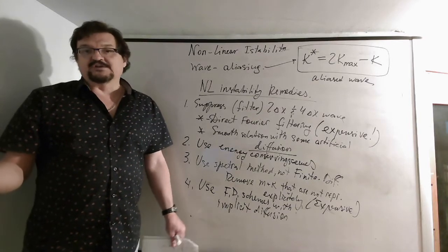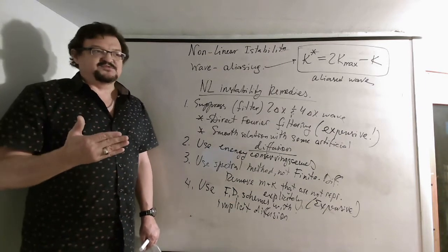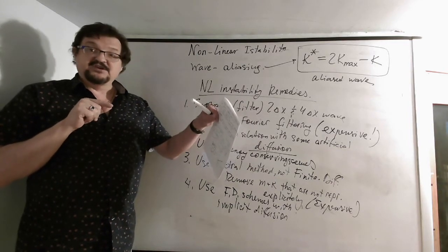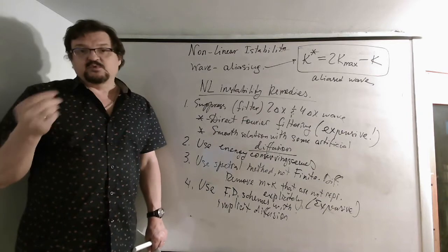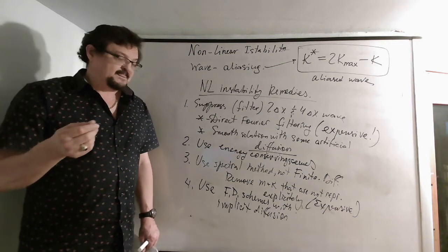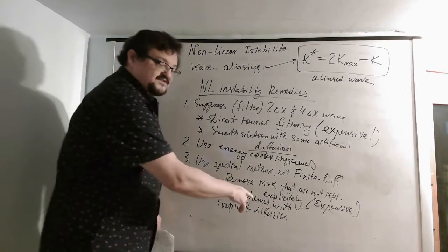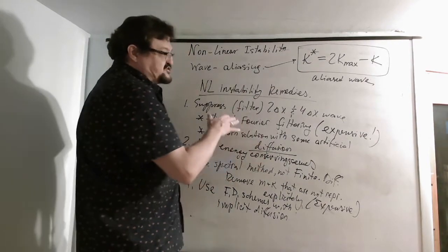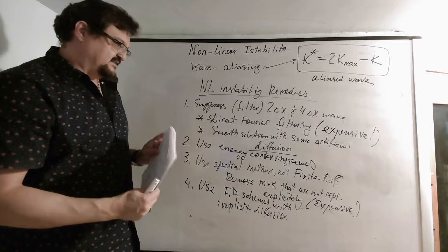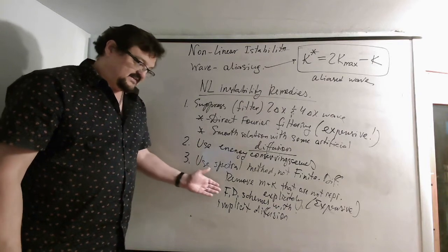But you could use a third order upstream biased scheme. We didn't consider it here, but if you use a pattern of, let's say, 3 grid points instead of 2, it's a third order upstream biased scheme. It will be dissipative, but not as much as the first order upstream biased scheme. So it will provide some artificial implicit diffusion that will naturally remove or control the 2 delta x and 4 delta x waves. So that's an approach that is plausible, and sometimes it's the only way.